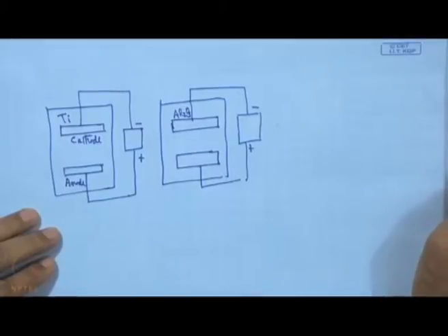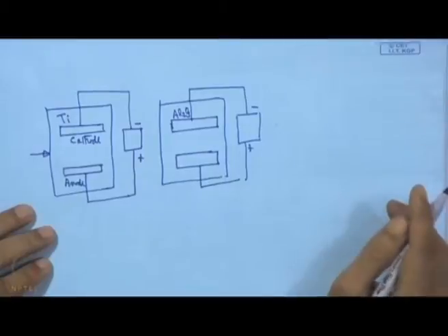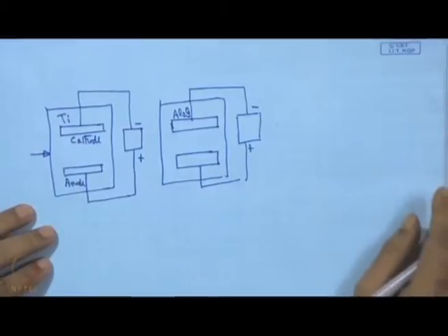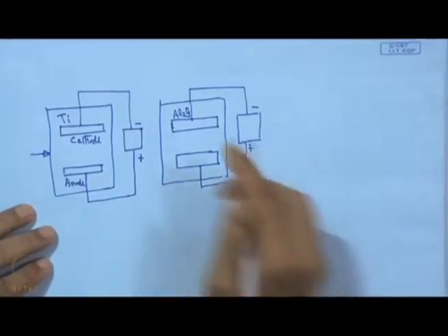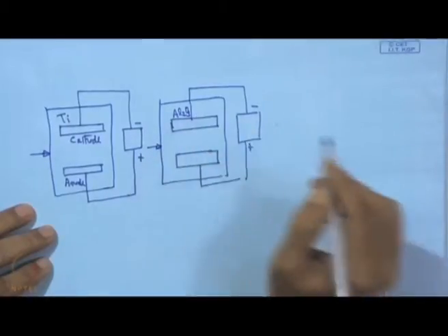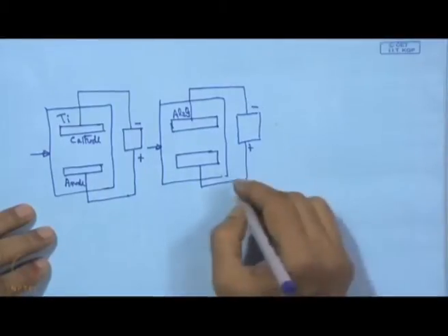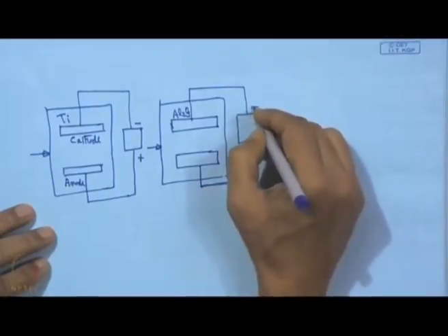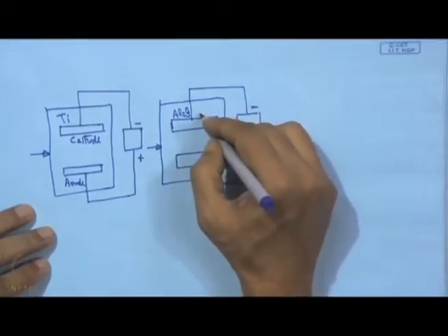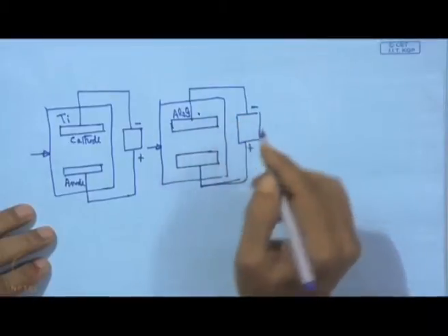Now, in this case we have all the relevant or required features of sputtering. However, one thing that is missing here is the conductivity of this material. As a result, the target will be polarized and there will be accumulation of charge, with no conducting path.